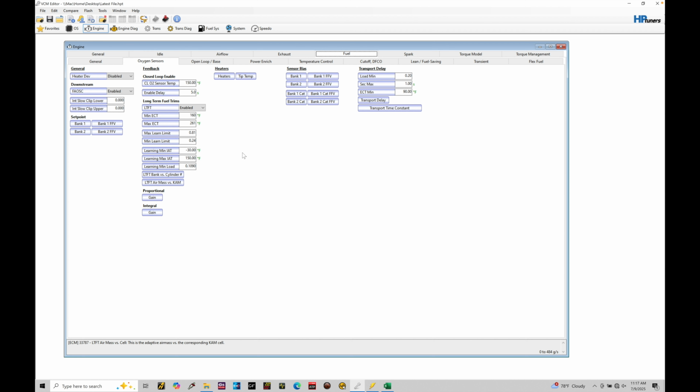Now, if we've put in long tube headers, spacing the oxygen sensors further downstream, we're going to find that the response time of the sensor reporting the actual lambda reading is going to be off a bit, because we're probably spacing it down 20-30% from its original location. So as a result, we have to go in and deal with this transport delay table.